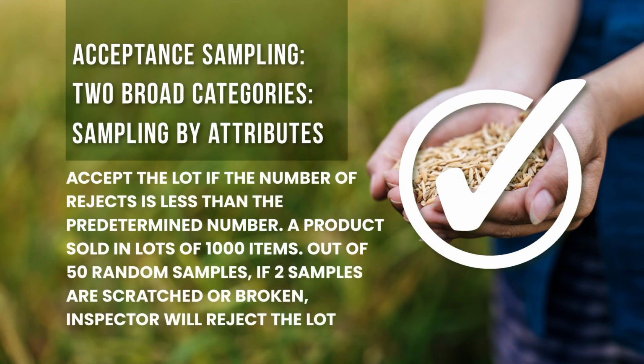We know very well, and this point I must really emphasize very clearly, that arsenic in water is present, widespread contamination of groundwater with arsenic. Now, can we afford to have attribute sampling for arsenic in water? Certainly not. So in those cases, we don't follow the attribute sampling. We follow the variable sampling. And in variable sampling, we quantitatively find out how much quantity of arsenic is allowed in the water, and we do the sampling for that purpose. So that is called sampling by variables.